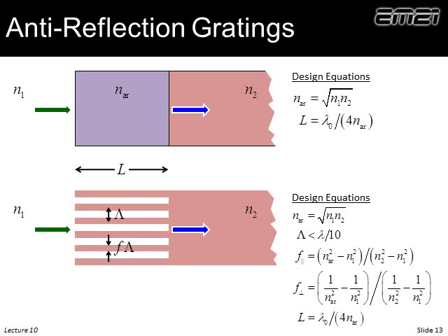Whereas on the top part, we would need a second material, and there could potentially be some interface issues. There could be some residual stresses if it's temperature cycling or having shock and vibration. That separate second material could delaminate or detach or fracture in some way. Whereas if it's monolithic, it's much more robust. So this is a pretty neat way to do things.